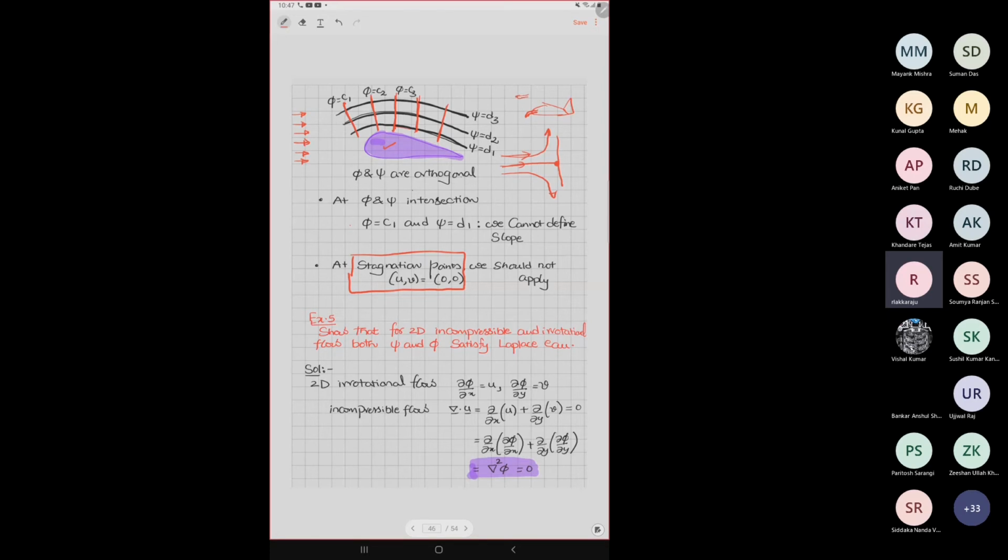And that is basically our pitot tube. Earlier days, when electronic measurements were not that strong, they used this mechanical thing. And that became an integral part of these aeroplanes. Even in the present electronic age you will have pitot tubes, because when electronic failures happen, these pitot tubes help the pilots to drive or steer in a better way. And the whole principle lies on the stagnation point principle, where the entire fluid is really brought to rest.